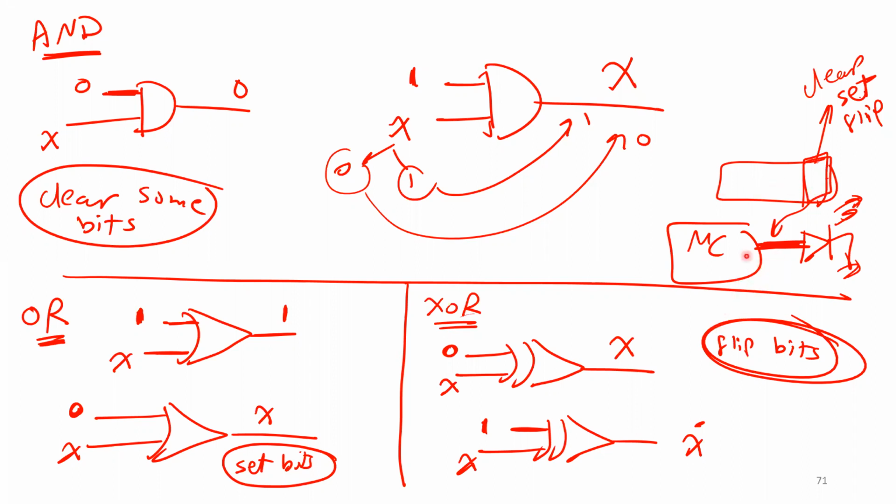So I have a byte here, guys. I'm going to do an OR operation with 1 here and zeros everywhere else. When you put 1 here, the result is 1, but when you put 0, there is no change. I'm not going to change this one. Is that clear, guys? Any question?